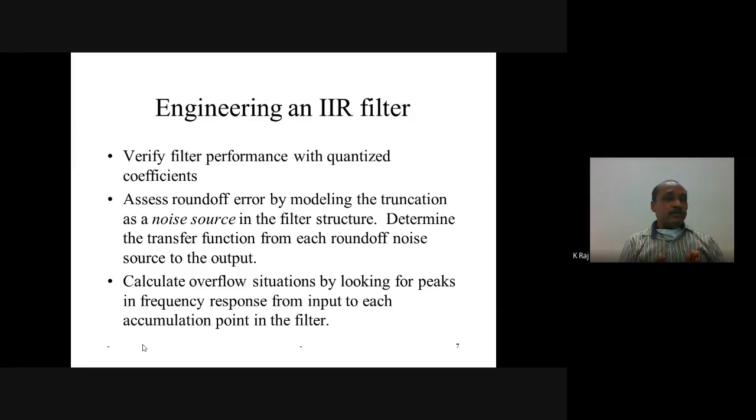So during the analysis, after quantization, we again have to analyze these four parameters: one is the speed, the second is the power consumption, the third is the space, and the fourth is the finite word length effect. On the basis of these performances, if the results are satisfactory, we can accept it and move on to the implementation and other purposes. Otherwise, there is a need for modification in the model of the filter or at another level of the design and implementation.